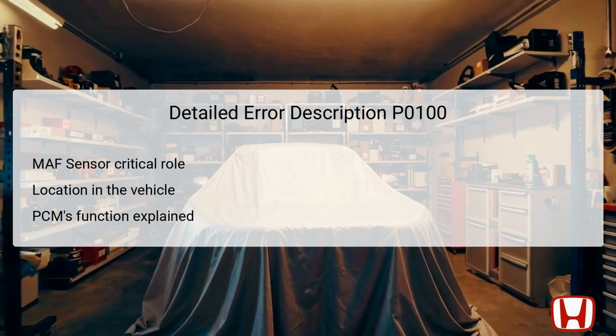If the MAF sensor circuit malfunctions, the PCM cannot accurately measure the incoming air, leading to poor performance and increased emissions. Therefore, understanding the sensor's location and its impact on vehicle operation is vital for diagnosing the issue.